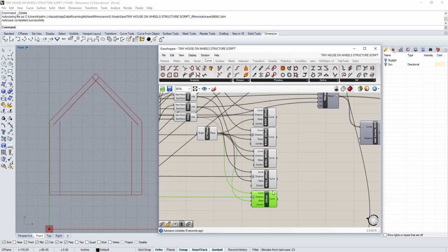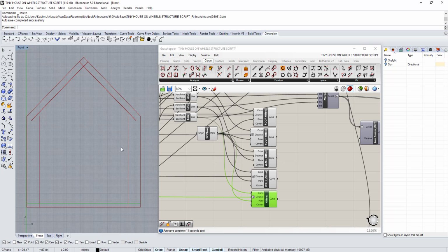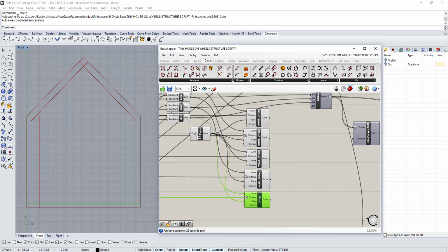So you see, if this depth of structure for the wall here was let's just say 2 by 4 or 3.5 inches, these lines would intersect, right? But since the depth of structure is larger than that, these lines do not actually intersect. So to make sure that these lines will always intersect, what we want to do is extend these lines some arbitrary distance that we know whatever value of depth of structure we give it, we will never exceed that value.